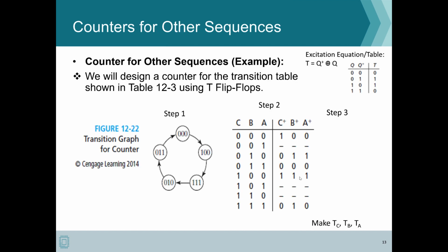So now we're going to see a simple counter. Here you can see the counter state transition diagram specified. There is no particular order in which this is going. It actually goes from 0 0 0 to 1 0 0, so it is not a binary counter. As you can see, it doesn't follow any kind of Hamming distance rule, so it is not a Johnson counter or any such thing. And also you see that sometimes there are multiple ones, so it is also not a ring counter.